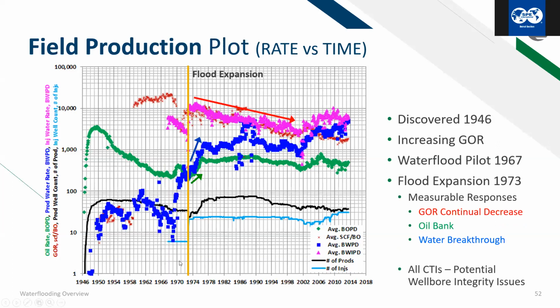What you will notice then is that these well counts don't exceed the original 60 wells that were drilled in this field. So more than likely, all of these injection wells were converted to injection. So they were previous producers that were converted to injection. So again, at this point, these wells are 25, 30 years old. Again, you're going to have to consider wellbore integrity issues as the wells age.